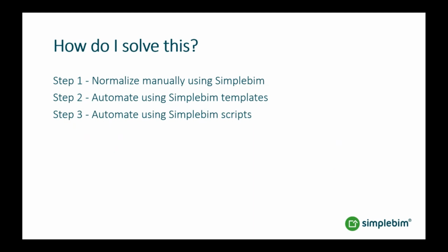But then you can go even one step further, which is the script approach. So once you figured out the whole workflow and you have confidence that everything is set up and working like you expect, you can run Simplebim scripts, which basically do the same thing, but without ever opening the Simplebim user interface. So you can do them kind of in the background automatically. But first you have to know how to do the first step, what you can do, how you do it.